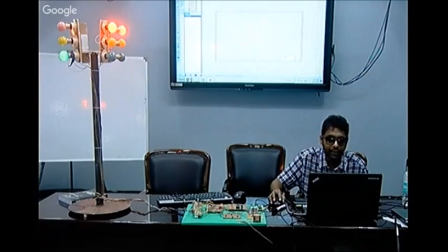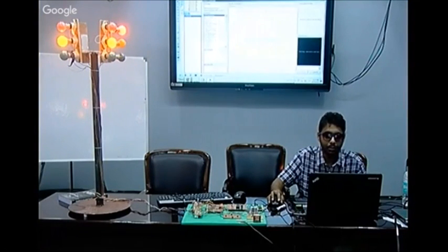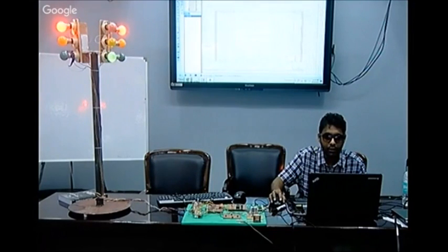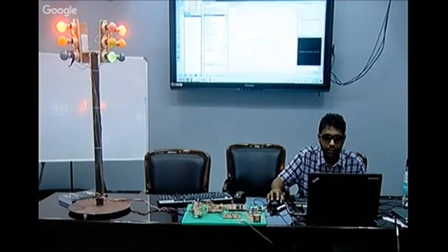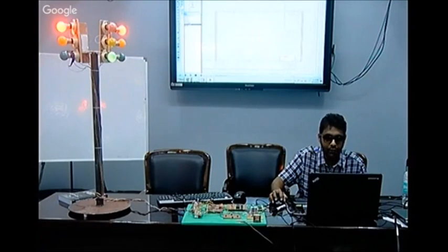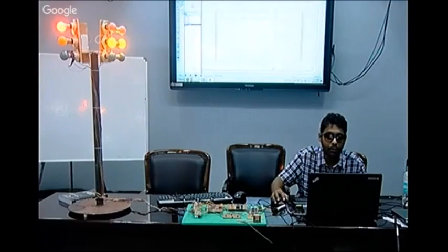The first step is to select the components, in our case. We have to click the D button, pick devices. After clicking on component mode, you have to click P, and this option will appear. If you select another section, for example terminal mode, and you click P, there will be no components. You have to select component mode first and then select the P button.